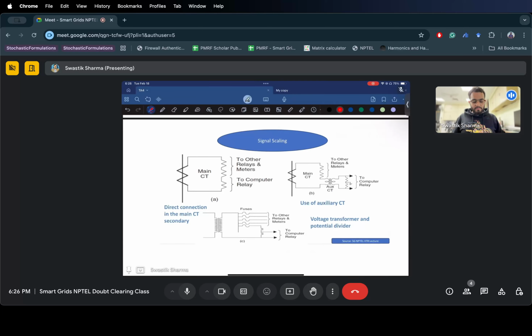And a relay cannot just take in values from the system. They use CT and PT, current transformer and voltage (potential) transformer, to scale it down. So in India, according to standards, the recommended input current is 1 ampere or 5 ampere, and for voltages it is 110 volt phase to phase, or 63.6 volts phase to neutral. So this is the Indian standard which we use.